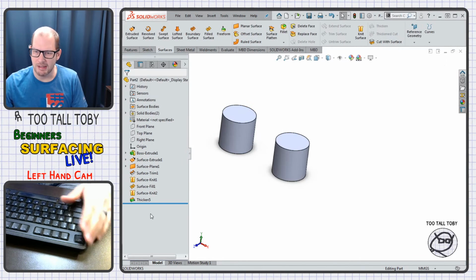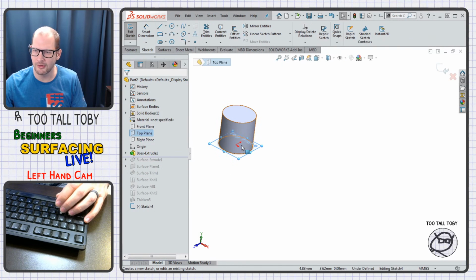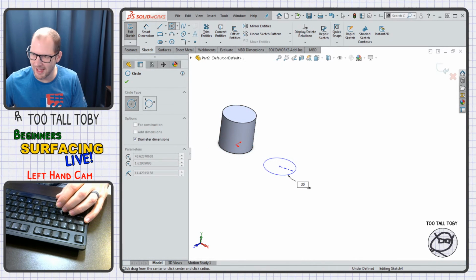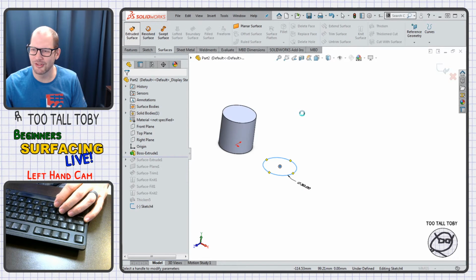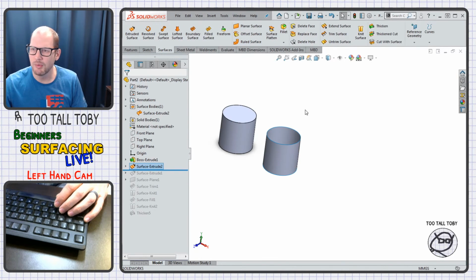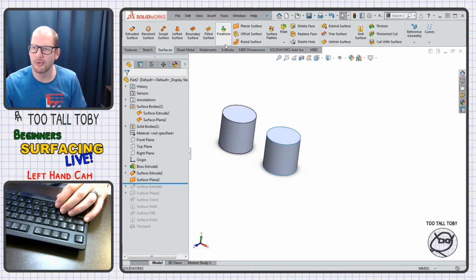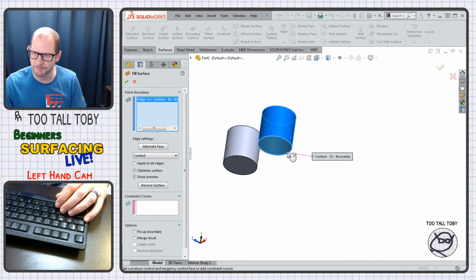So in summary, when you're working with surface models, the workflow often looks like this. You create your geometry one face at a time. That one was for you, Eric. We go here to surfaces, extruded surface, we make that 30. We go to, let's say, the planar surface command. We pick this edge here to fill in a planar surface there. We go to the surface fill command. We pick this edge here to fill in a planar surface down here.